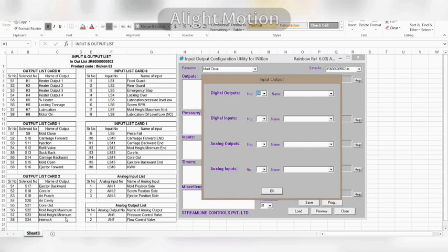If you want to show your own message in the PLC page, you can also type one which does not appear on searching. For example, in the wiring list, number 5 is percentage heater. I want to show nozzle heater here instead of percentage heater. So here in the number column we'll select 5, and in the name column, we'll type nozzle heater. So in my PLC, nozzle heater will be shown on number 5 of the page 5.